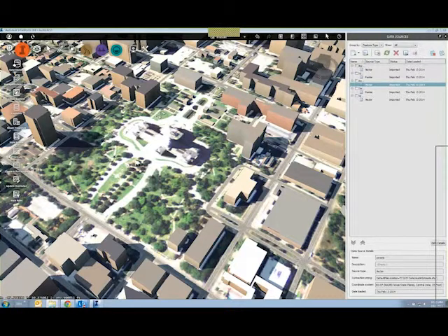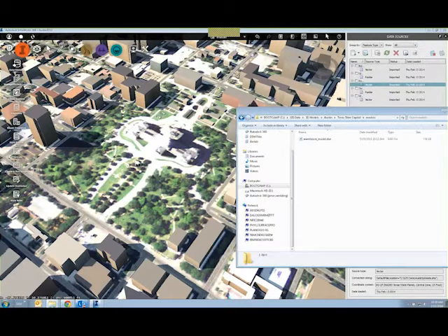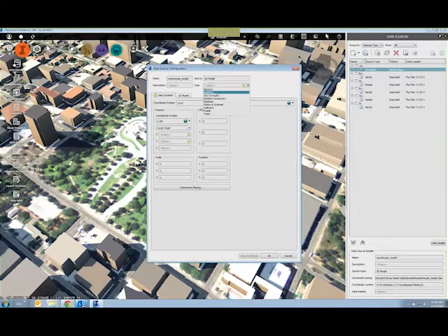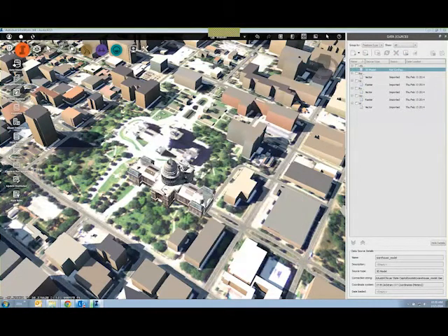And again, this is drag and drop. Just to give you an idea, I'm working with a DAE file, drag and drop right into InfraWorks. Tell it, hey, that's another building. And then I use the interactive placement tool to simply line that model up with my aerial